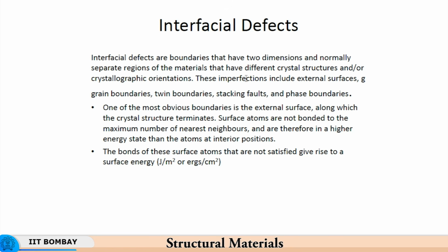So basically, in a particular phase, be it ferrite or cementite, there is homogeneity in the structure, homogeneity in the lattice spacing, the layout of the atoms present in that particular phase. Therefore a phase boundary is the one where this orderly nature is disrupted, that is, broken. So you have a phase boundary as a two-dimensional defect once again, because the phase boundary being a region of mismatch results in further weakening. So you have grain boundaries, you have phase boundaries. Similarly, you have twin boundaries.